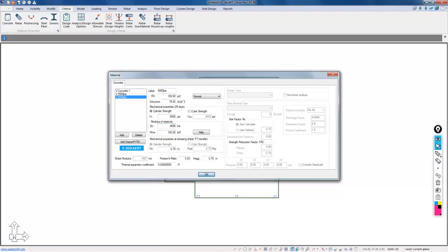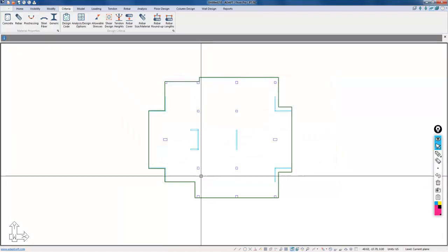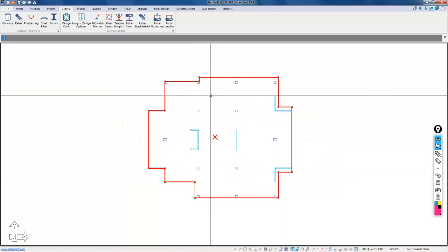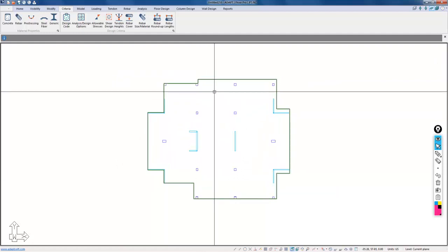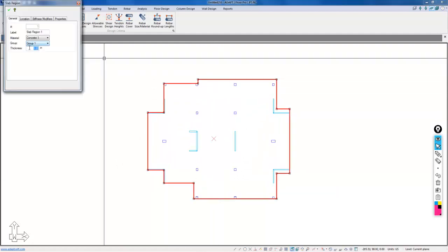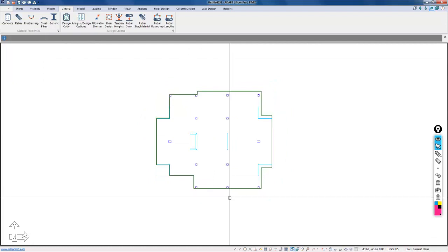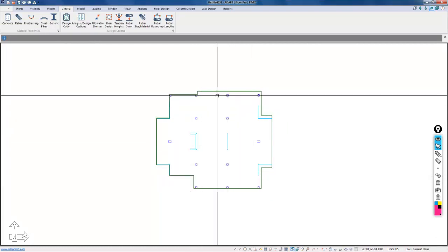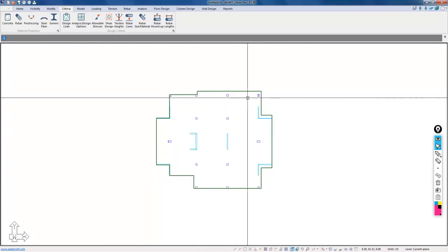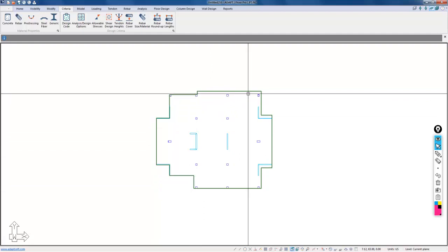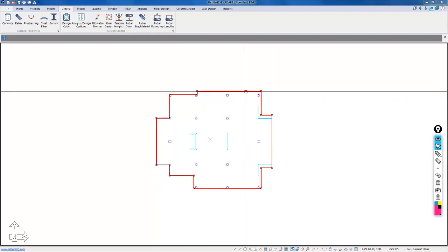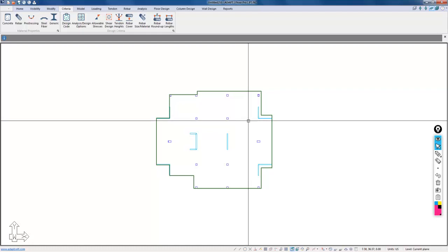We'll select OK, and we're now going to go ahead and make sure that these materials are assigned. So if I select the slab again, we're going to select 5,000 and I'll press the green checkbox to accept that. I want to also select the walls and columns and change those, but there are multiple walls and columns. Here there's only one slab, so I can go ahead and open that one input.